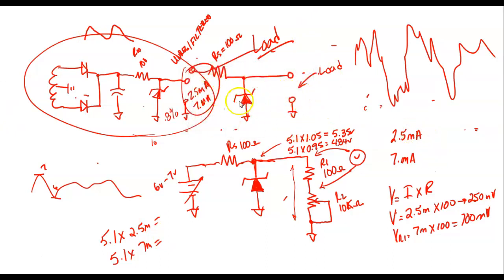And if we looked at the actual schematic of these 3 terminal regulators, you'd find out that it's using a Zener as its reference. Somewhere in that schematic, it's going to use a Zener. But they're getting a lot more current gain out of other electronic devices, plus circuits that sense overcurrent and undercurrent.